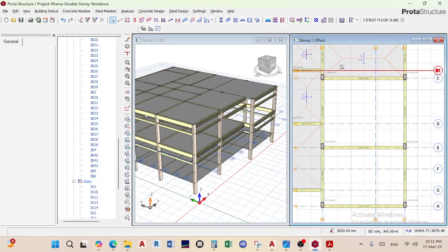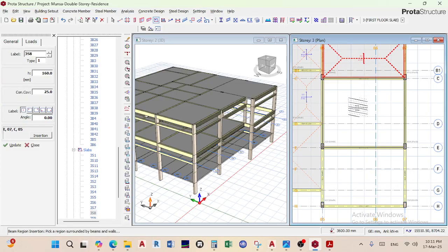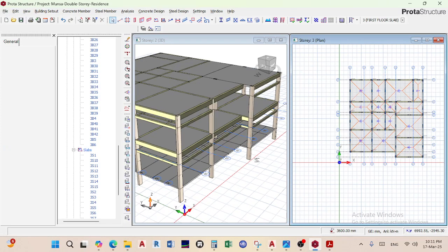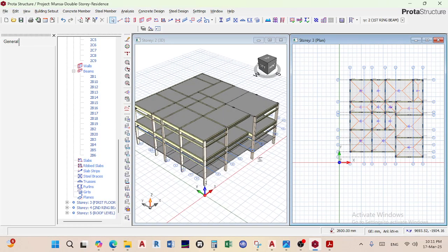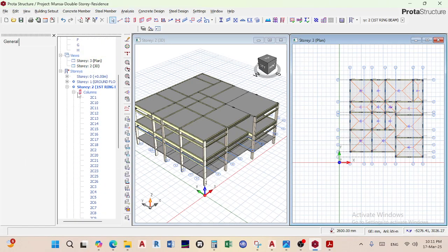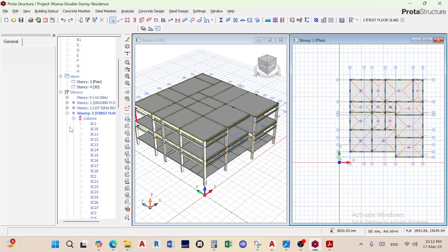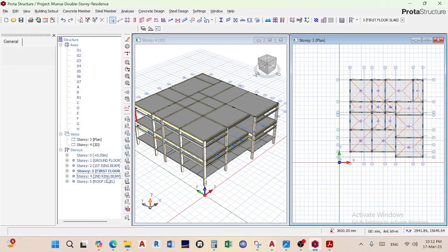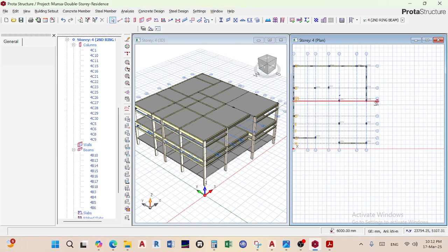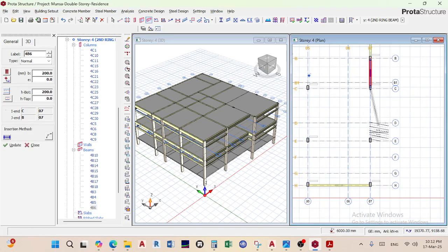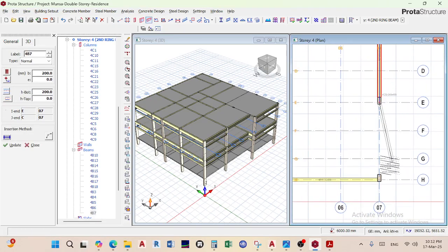Okay, this is good. And then I'll select the properties of this beam and put it there and there. I've closed it up now. It's good. So where else do I need to go? I need to go to my story 3. Select it like that. To the second ring beam. Sorry, story 3. I can see that I need a ring beam to go from there to there to there.